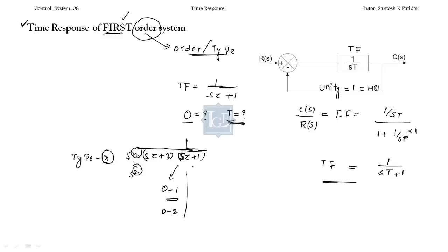Okay, so the poles which are located at the origin provide the type of system. Is it correct? Suppose you have a transfer function like 1 by s square (s plus 1). Suppose someone asks what is the order of the system and what is the type of the system. So order over here will be 3 and type over here will be 2.